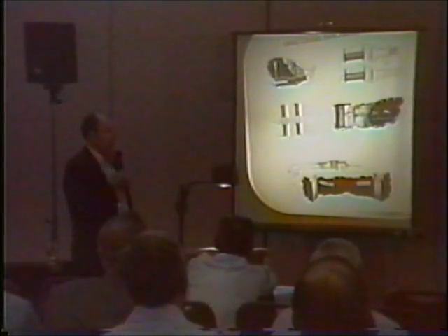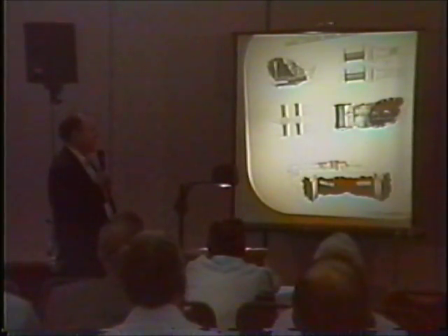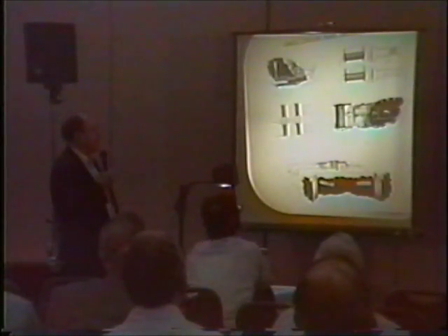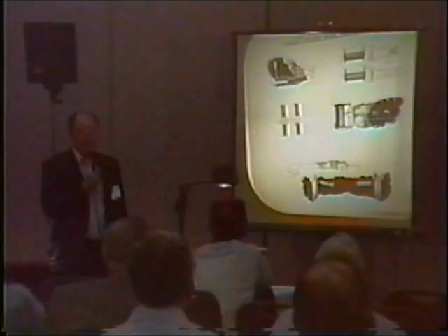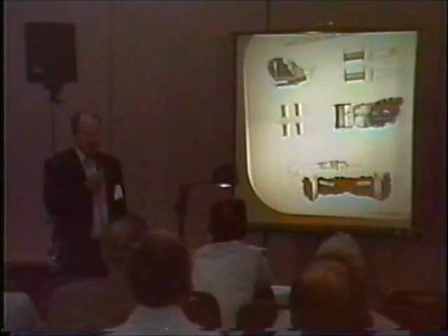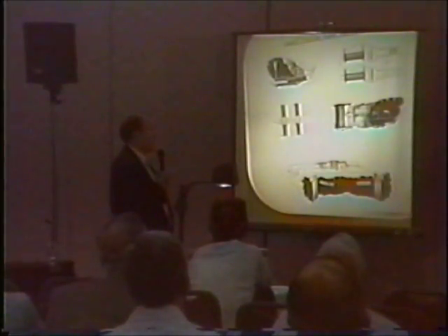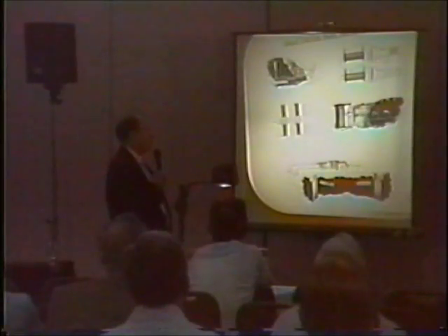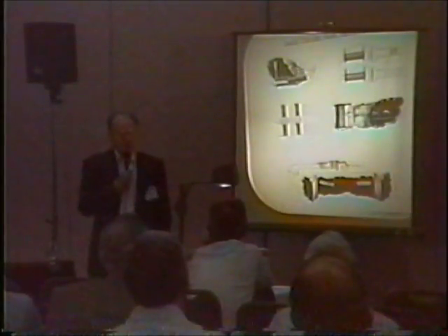Number two drawing there is showing the capacitors combined with the output, and the top one there is set up so that you can run a conventional transformer directly. And if the frequency of the coil is something other than what you want, on that number 2, just slightly above where the number 2 is there, you can put a resistor or a capacitor in parallel across that particular coil there, and you can bring the frequency down to where it will match your transformer.